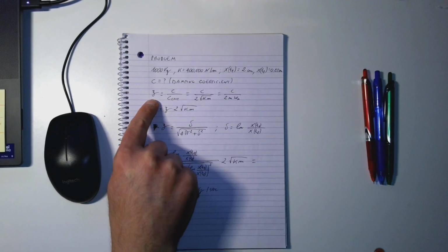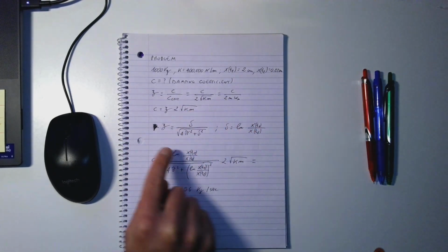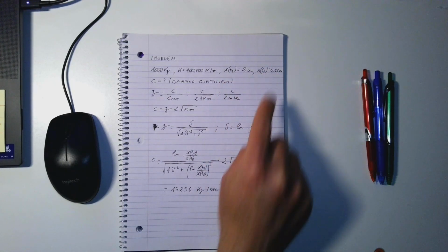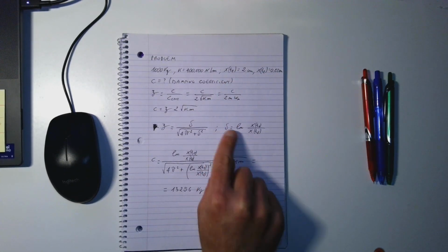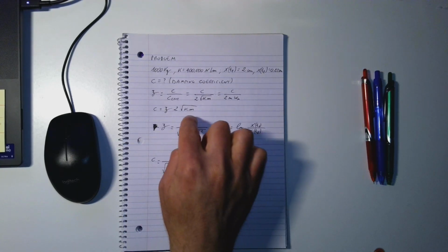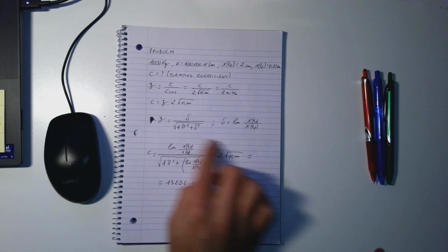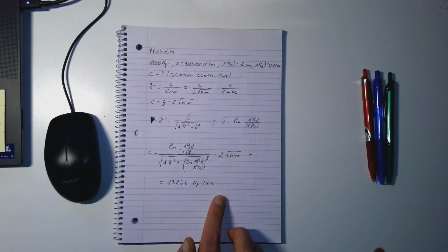We know the relation between damping coefficient and damping ratio, so we can rearrange this one. From the responses we can find the logarithmic decrement, then we can plug here, and then we can find zeta. Here I just plugged in all the quantities, so we have only one final equation, and when we plug in all the numbers, this is what we obtain.